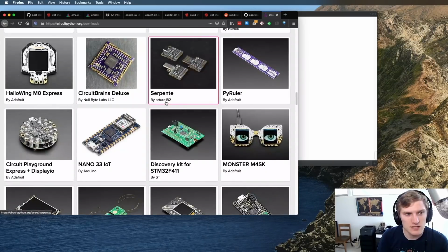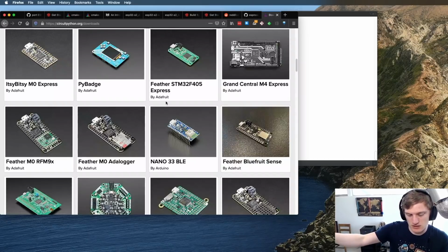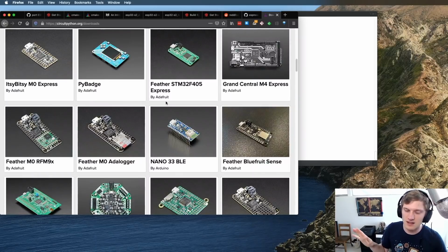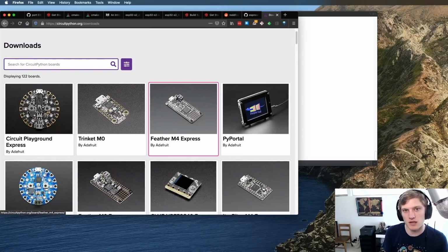And I found CMake's notion of toolchains, which is how you can tell it like ESP32-S2 is Xtensa, SAMD21 is ARM Cortex M0. Like we can do toolchains for that level, but it's not quite clear to me where boards fit in that case. And so if you have an idea how that would work, I've been looking for embedded uses of CMake to see if anybody's kind of figured out a best practice for it. And I've only found that, oh, you should use toolchains to define your ARM toolchain versus your Xtensa toolchain. So I'll dig into the ESP32 IDF to see how they do that there as well.